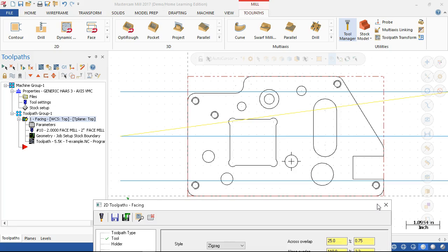So usually the facing operation is going to be between 5 and 10 thousandths. I want to take a minimal amount of material, get this as clean as possible, and have plenty that when I flip it over and remove it, unless it's just a lot of material, I'm not going to have to remove a disproportionate amount on the backside. I'm going to go ahead and let it take a skin pass on one side, rough pass on the other side, and then go back to the skin pass if I need to.